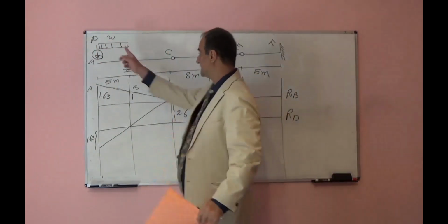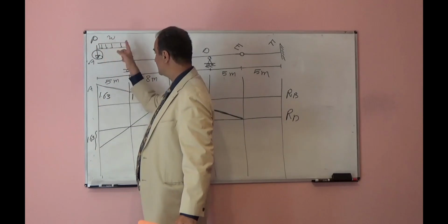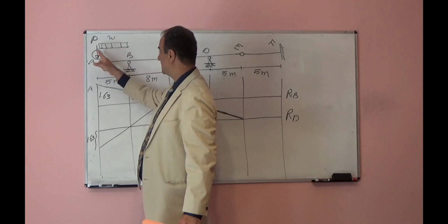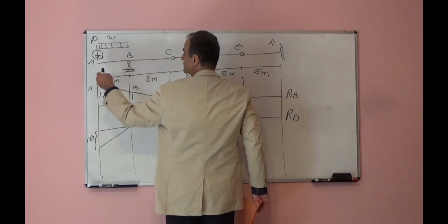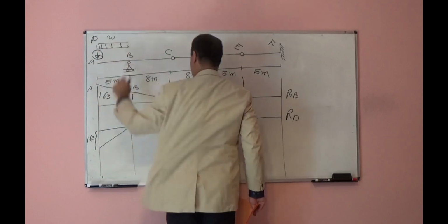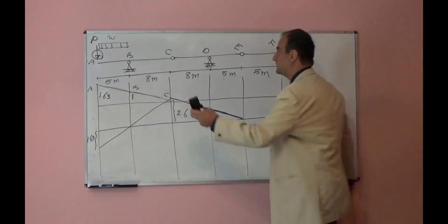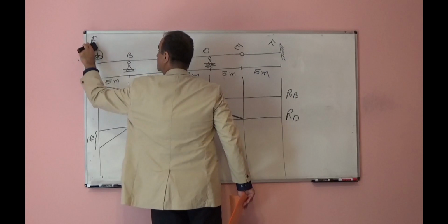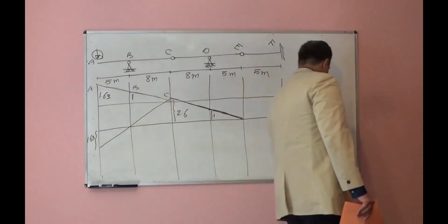So the intensity W times the area underneath of this from A to B. You see this load will occupy from A to B. So the area from A to B in the influence line you will find, you will multiply by the W. Of course, I will prove that area later. But here it is good you know it from now, but I will prove it.